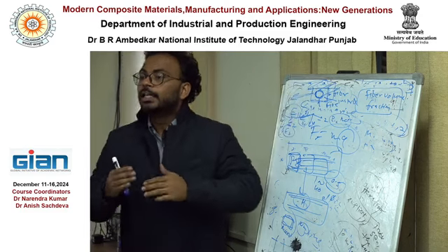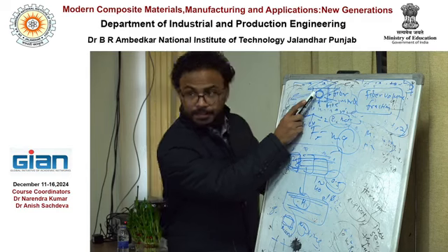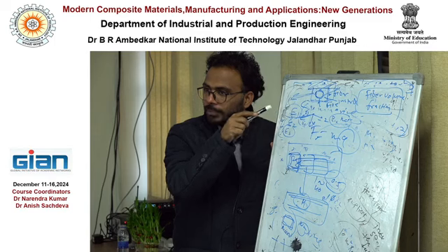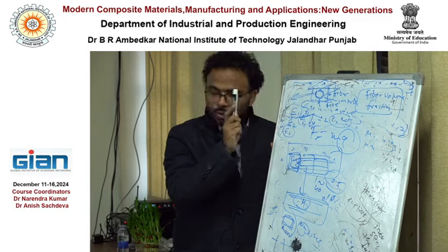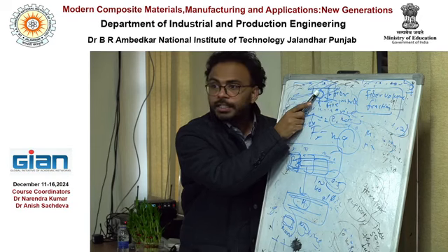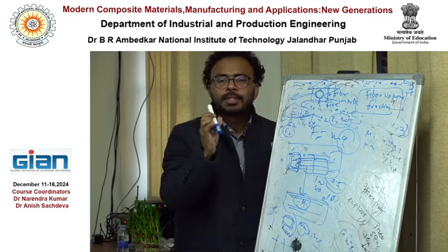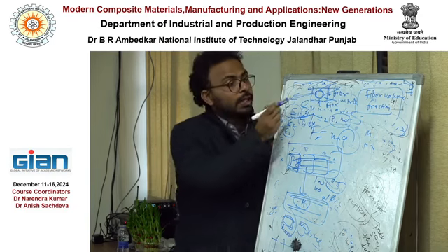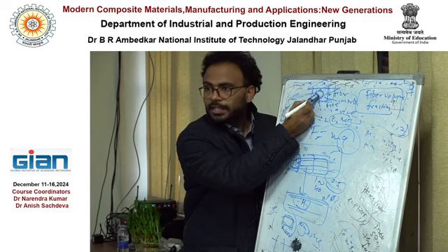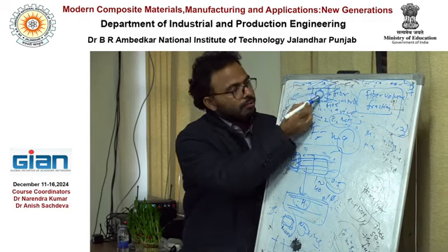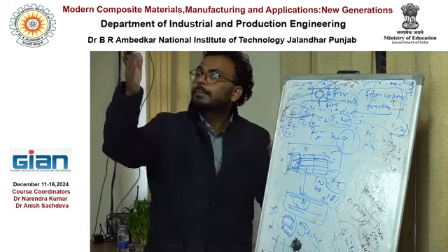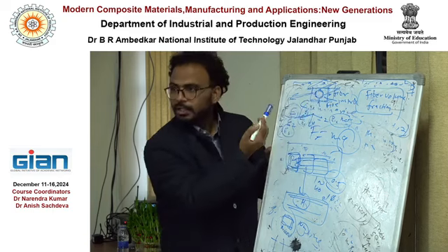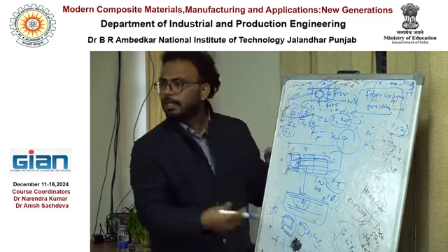Then you have a variation of the engineering constant through the thickness. You have to learn this in Abaqus. You have to give a subroutine. In this, when you put the fiber properties, only the fiber varies, right? Fiber only varies, no matrix. The matrix, the resin, is the same. So you have to vary the property from here to here. If you search for engineering constant variations according to thickness, you can vary the E of the plastic up to this thickness, E something like this thickness. So you can vary E from here to here according to your material. Getting the point? So you can give the material properties of the fiber and the matrix, do the same thing, and do the mechanical properties, macro analysis, right?